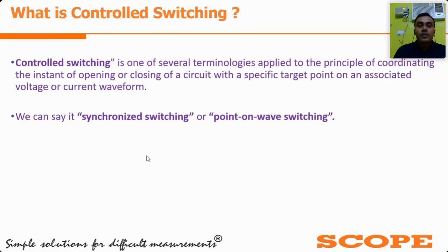So it synchronizes the command with the bus voltage, and as a result it gives the command to the breaker after some delay, and finally the breaker electrically closes at voltage peak. So this is the main work of CSD: it controls the switching of the breaker.